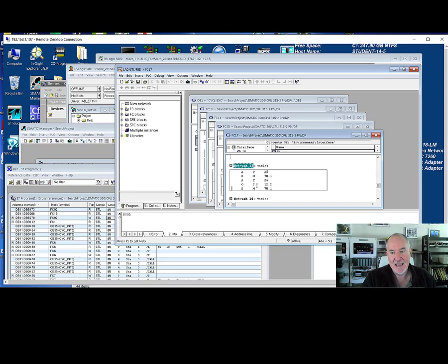It might be a remote PLC that took an entire word's worth of data or a block full of data and wrote it into the memory of that data block. It could have come from somewhere else. But I'll always run into one of two things. I'll either run into some kind of a physical input, or I'll run into something that doesn't have a write command in the PLC. So be careful if you don't find a write command in the PLC. Look at whole words or whole blocks that might be affected. An example would have been that data block.